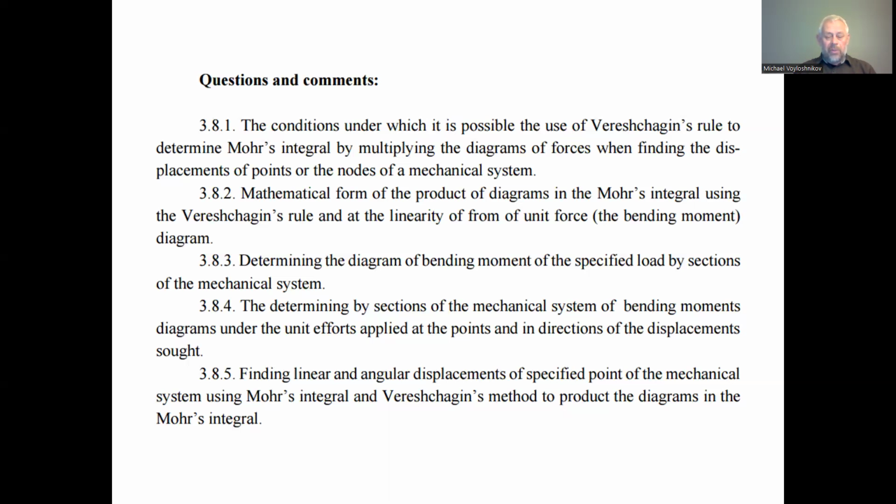After that, we can use the Vereshchagin rule if we do not have the mathematical equations of the diagrams of the bending moments and have only the magnitudes of the bending moment at definite points. To use the Vereshchagin method, we first find whether one of the diagrams, usually the diagram of bending moment under the action of unit forces, is of linear shape.